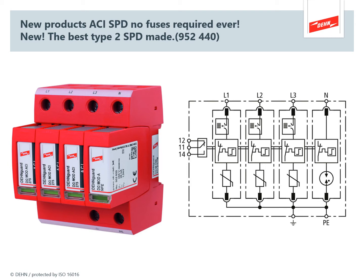But what if part of that circuit became a short circuit? So there was an internal fault and then we have a high fault current. Under these circumstances, it is the upper component, the spark gap, which guarantees that there would be no nuisance tripping and no such fault flowing. Therefore, because it is a spark gap and there is no continuity anyway, there is no need for the fuse external in this circuit.